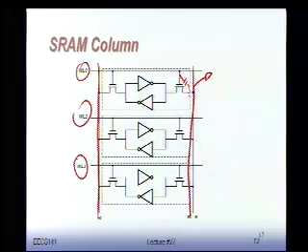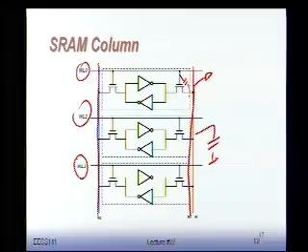So you have 1,000 bits on our thing. You can say, let's say a femtofarad per bit. 1,000 times a femtofarad is a picofarad. Okay? So it means if I want to do a read operation, I have to be able to move that picofarad up and down. It's not easy. And it's even harder because typically when I drive a picofarad, what do I do? I put a giant buffer in front of it. But I'm not allowed to do that because I cannot put a big buffer in every one of those cells. I want to keep them small.